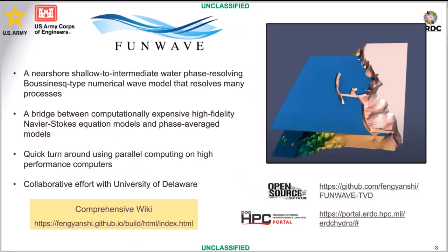It works best in coastal areas where you have complex geometry and bathymetry that the spectral wave average models may not be able to accurately estimate wave diffraction, refraction, and run up. Those nearshore transformations around that geometry. FunWave is pretty good at that.